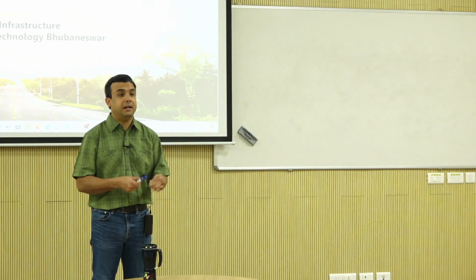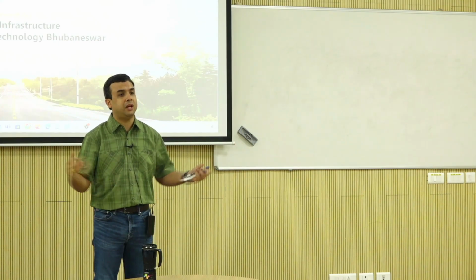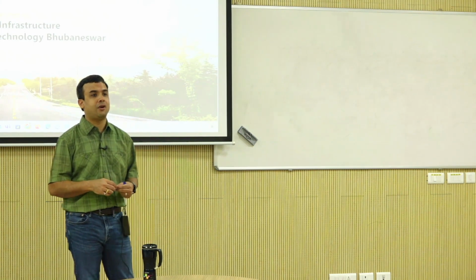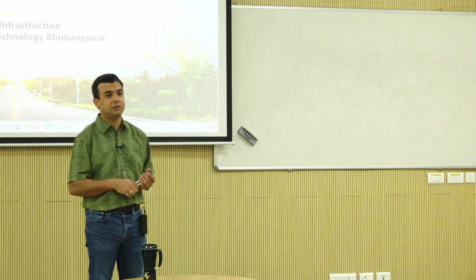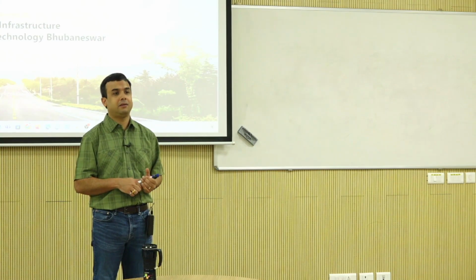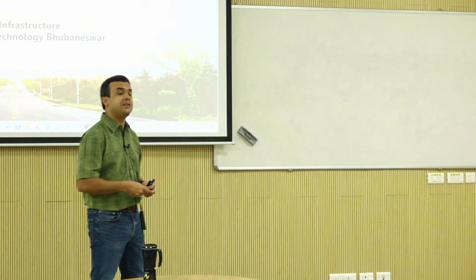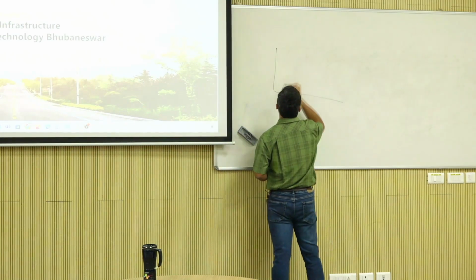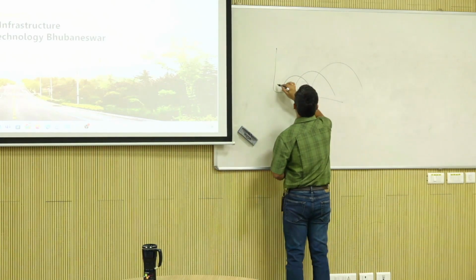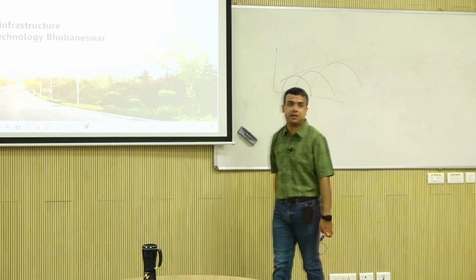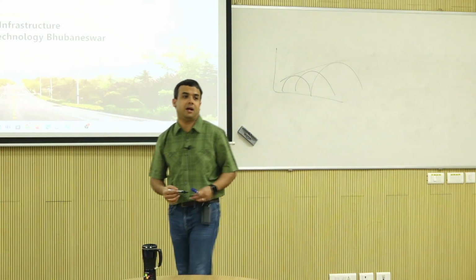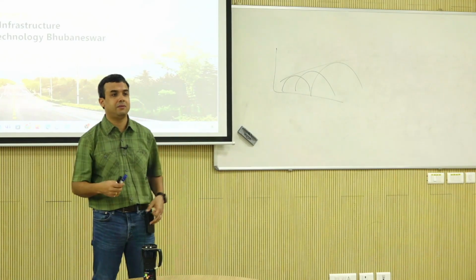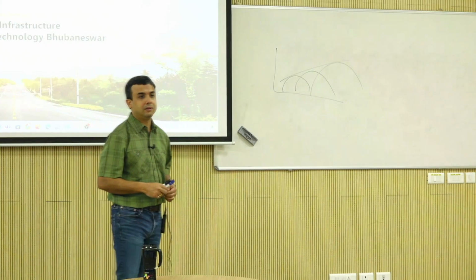Are you able to run a shear strength test? Can you apply confining pressure and shear it? Is your device strong enough to shear that material, or is it too strong? You have seen resilient modulus, but if you do a triaxial and you are able to plot a Mohr-Coulomb envelope like this, then it answers everything. That it's a frictional material for sure. Try three different confining pressures, at least two. Do you see a difference in shear strength? That will work.